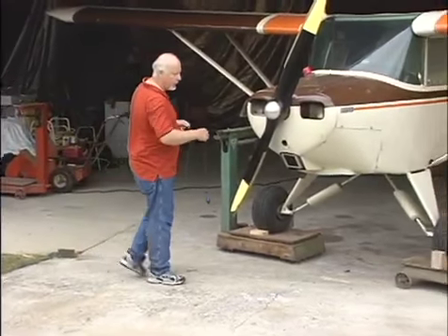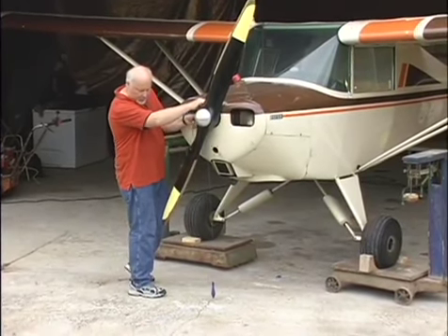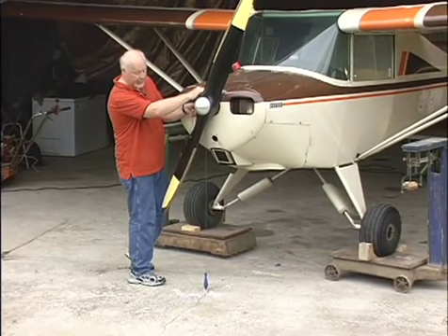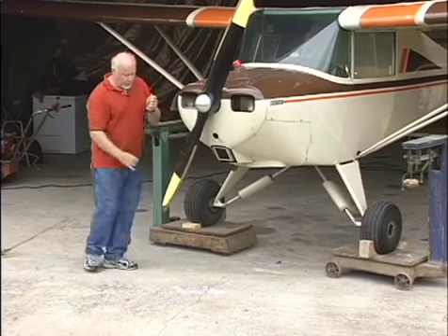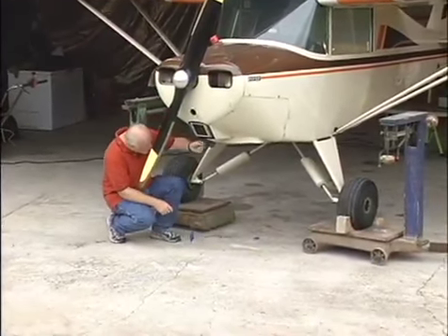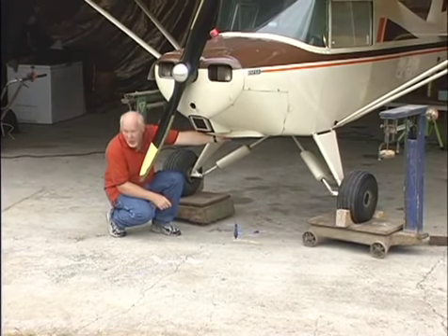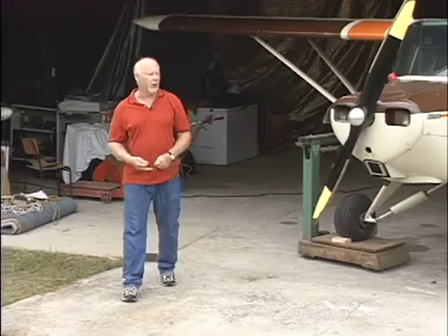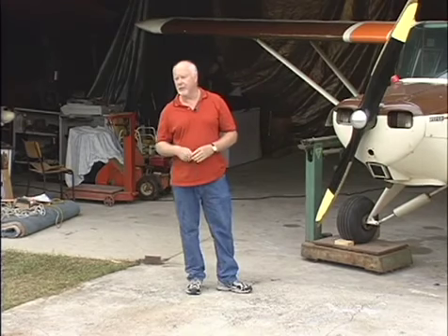We ran a line down from the back of the flange on the prop, which is something that's not very useful to us today, but for somebody in the future, they have a reference. We also marked the firewall, and again, we're just recording that for future reference for someone. If they're adding or taking something off the aircraft, they have an area to measure from. It's easy to measure, rather than going through a whole weight and balance again.